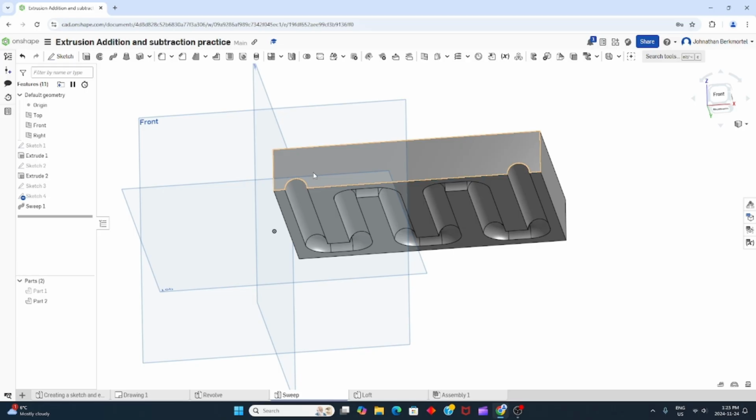So like let's say the profile of a computer mouse that has a lot of curvature faces on it, where we would use lofts and sweeps to create the component, where a more blocky looking object would require the extrude and revolve function, where if we wanted to fillet the corners to make things appear more smooth, that would be the solution.